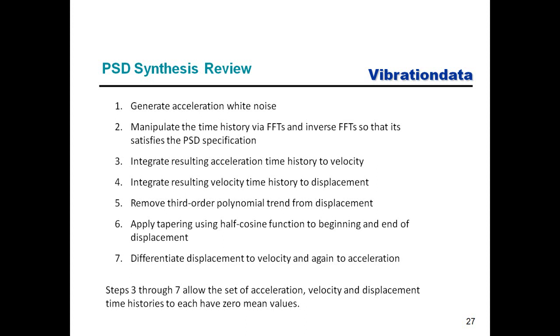I take that displacement function that's been cleaned up from step 6 and differentiate to get velocity. Then I differentiate again to get acceleration. So that's how I come up with a corresponding set of displacement, velocity, and acceleration, where each one of those 3 signals oscillates about the zero baseline. And that works out pretty good.